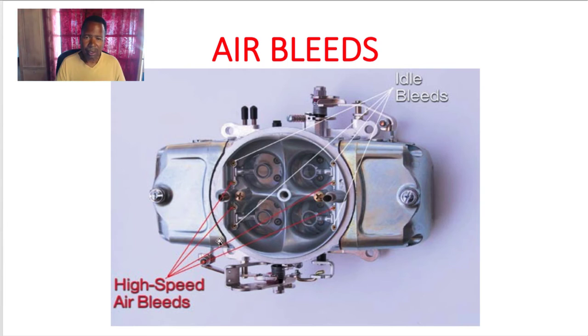be cleared also. The rule of thumb was when we used to rebuild carburetors, if it has a hole, blow through it. Blow a cleaner through it when you have it apart, because you don't know if it's an air bleed or not. Just blow air through it.